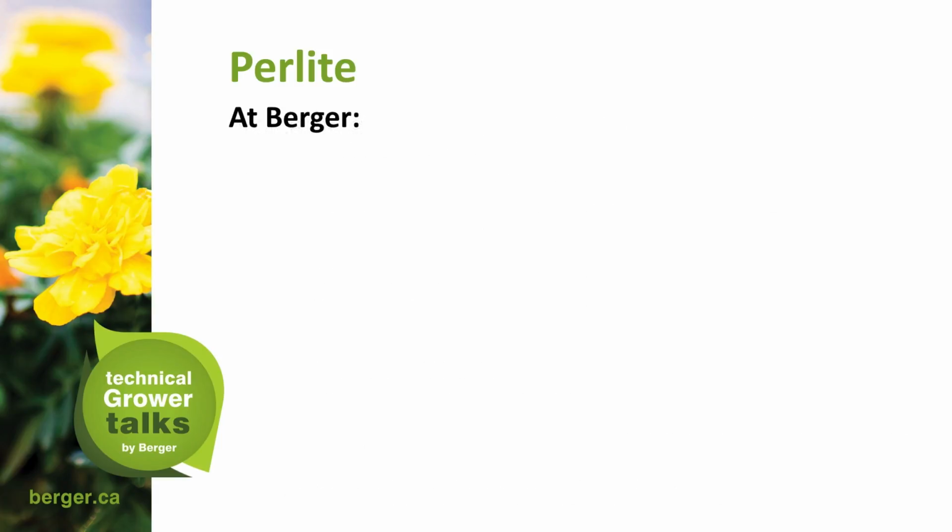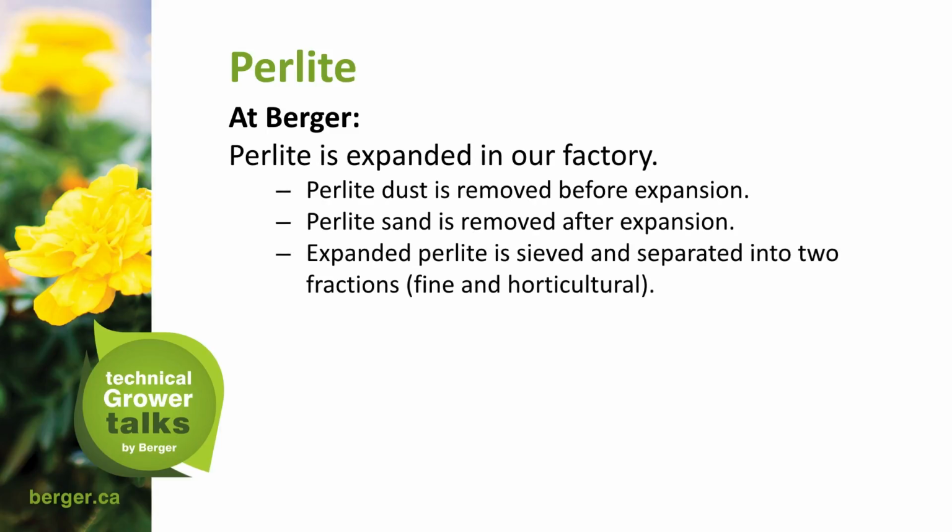At Berger, perlite is expanded in our factory. Perlite dust is removed before expansion. Perlite sand is removed after the expansion. And we end up with an expanded perlite, which is sieved and separated into fractions, fine and horticultural. Fine is used in our germinating mix, the horticultural in our regular standard mixes.